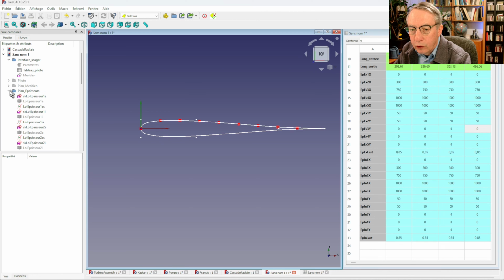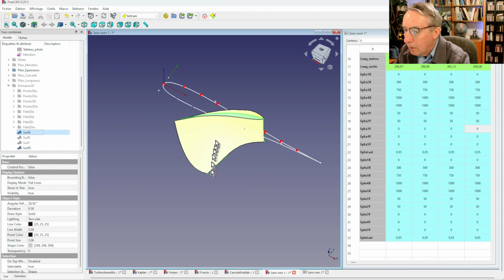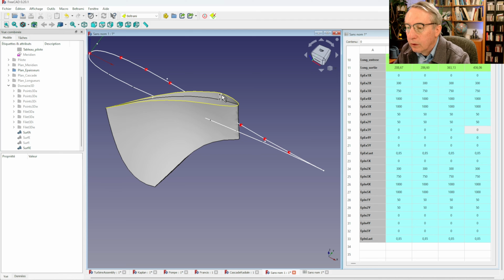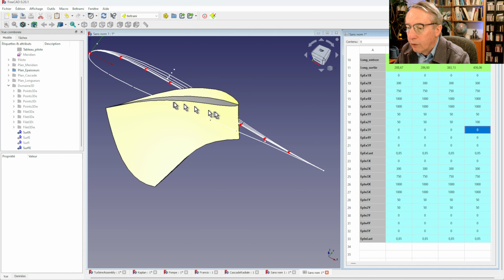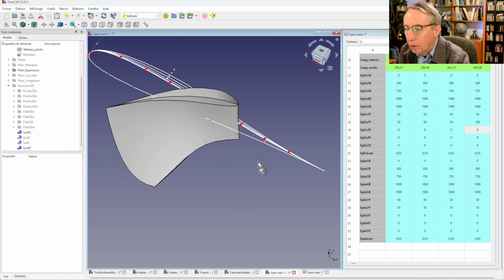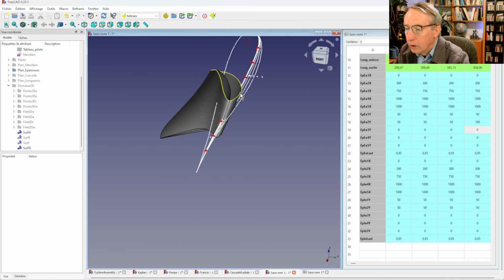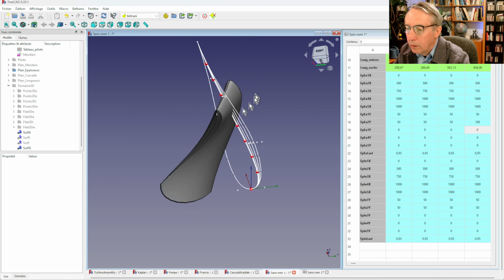If we display the 3D result with the web, if we want to increase the thickness at the crown, the thickness at the crown, the maximum, will be defined at the pole 2 on Y definition, and presently it's 50. If I put 100 and launch the calculation, we see that everything on pressure side remain constant, but we see that the profile has been modified on the suction side at crown, but not at bend.